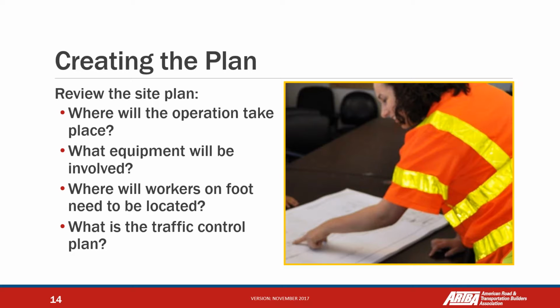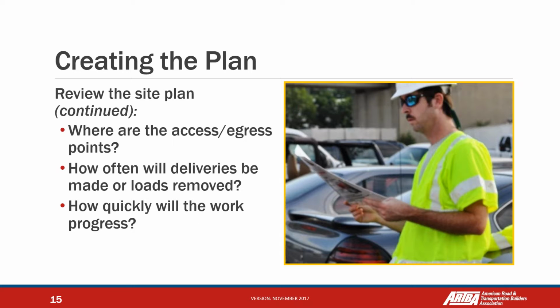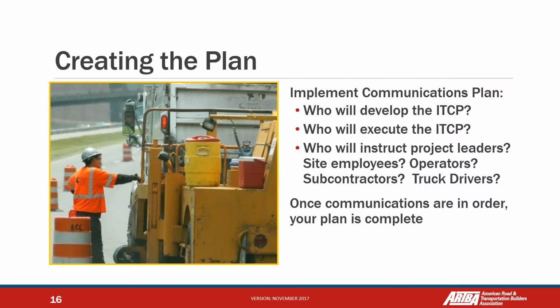Then what equipment will be involved? Okay, I need this equipment, a dump truck, I need a water truck, I need here a roller, a paver, and other equipment that we need to use. Where will workers on foot need to be located? Designated special areas for workers on foot, different from the traffic area. So where are the access and exit points? How often will deliveries be made or loads removed? How quickly will the work progress? So how much time do we have to finish the project, and so on.